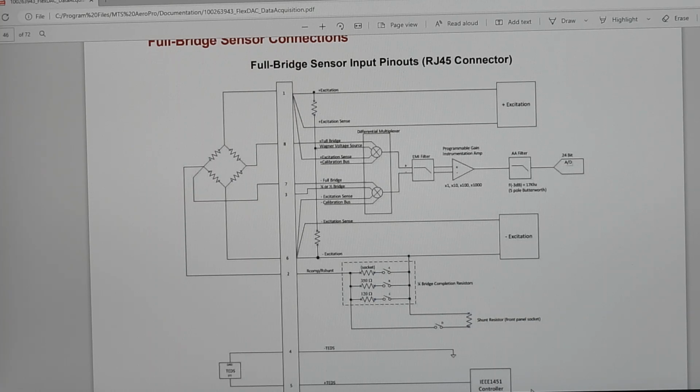Well, we can always take a look at the HWI file and see what those are configured as. Also, the spec sheet would be something to dig into on those to see what they are. I've only configured a few. I thought the Temposonics that I've dealt with have been digital. I don't think I pulled them into ducts. I thought they had to go into a logic level digital input. I'm talking about the ones that are on the actuators, the MTS actuators, the internal ones.